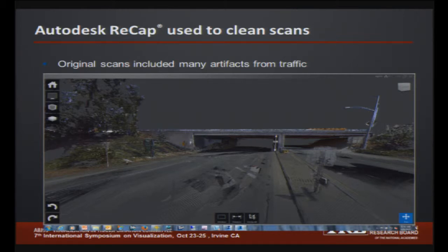What was the size of the point cloud scan? A few gigs. I don't remember exactly. I don't mean that way. I meant how many points, because with most of the vendors you can select the density. Yeah, it was Faro. He had a process for how he picked his spacing, trying to get us close to an inch if he could. There's a spec in his proposal, and I don't remember exactly what it was, but that's the critical thing: know what kind of data you're expecting from the vendor and specify it.